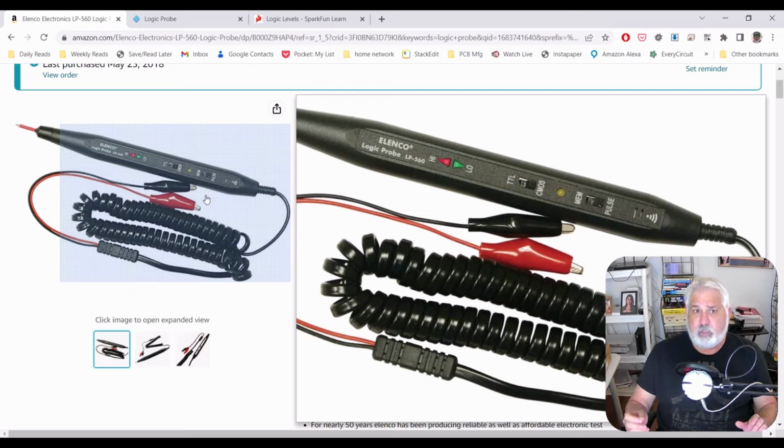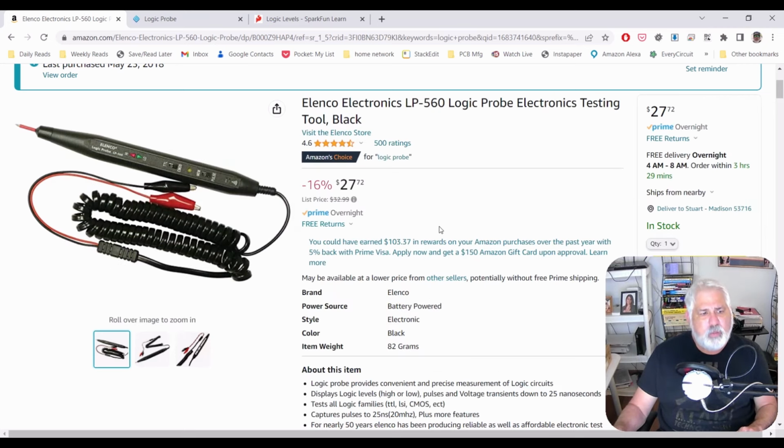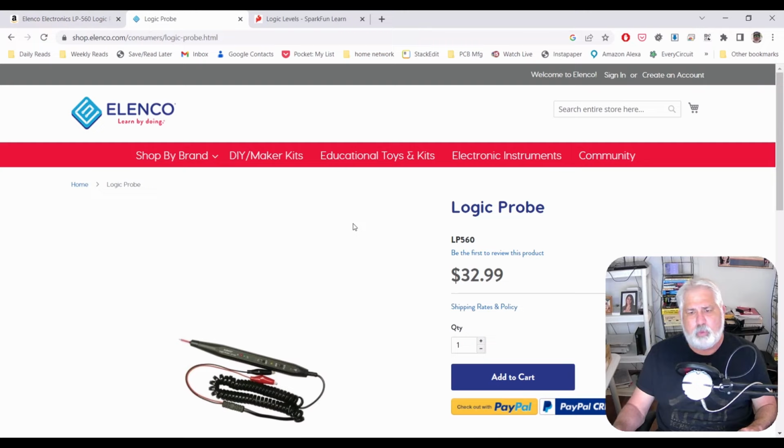Pulse tells you that there's a pulse train coming through. What is a pulse or pulse train? Basically, it's a signal being sent through, typically serial. You can have parallel ones too, but the point is that it's a series of ones and zeros in some order for the data that's being sent through, and it's happening maybe so fast that you can't really see the high and the low going. And instead, it tells you, hey, there's a pulse coming through. So with that, let's go take a look at the manual real quick.